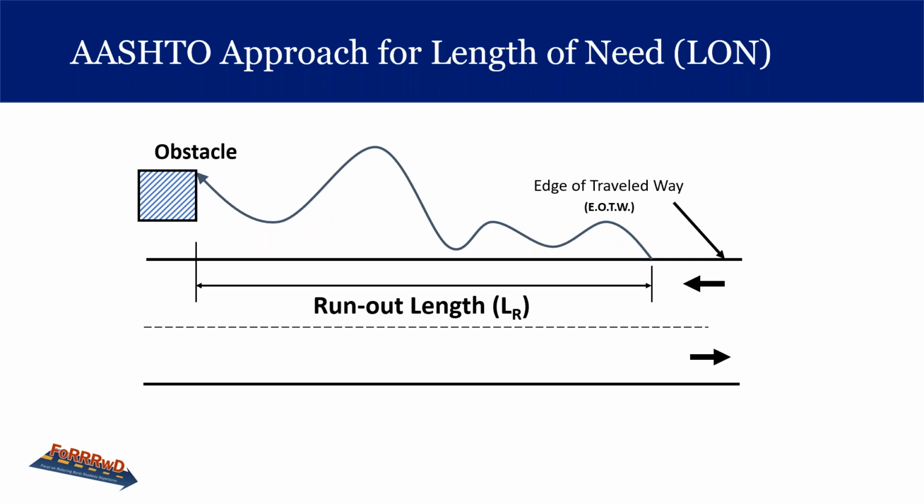All we really know about the angle is that it decreases at higher speeds. So the AASHTO design procedure does not specify any encroachment angle. Instead, it uses a run out distance and a lateral offset to the backside of the hazard to determine an appropriate barrier design. The assumption is that a driver will try to bring the vehicle under control and try to return to the roadway. If he or she is behind a barrier, then the only choice is to bring the vehicle to a stop. So the whole process hinges on the run out length, defined as the stopping distance off the pavement.